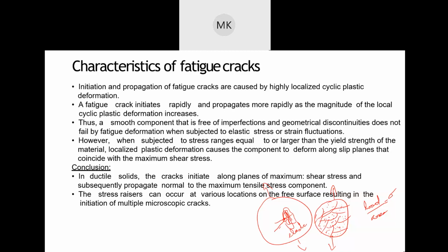So the major thing that you can do is, let's say I have the same thing and I have minor cracks at 100,000 places. But if my surface is smooth and polished, I'm not going to generate a surface crack at all. So the material, even though it has hundreds and thousands of small micro cracks within it, since I don't have a crack initiation at the surface, will still survive.